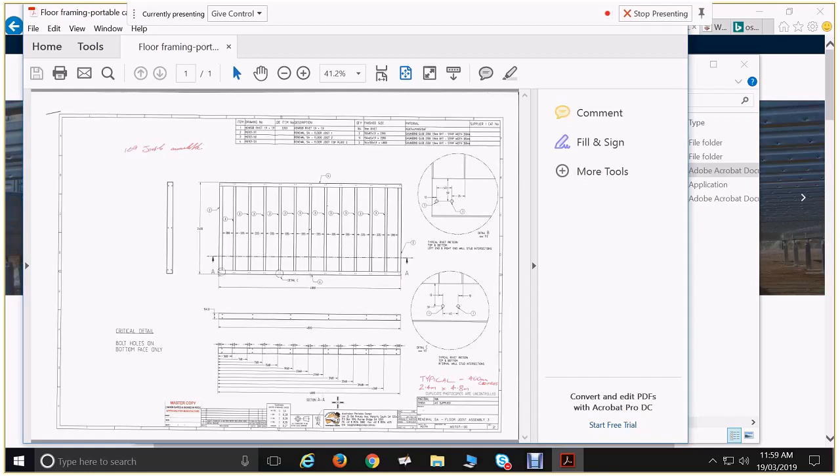So there's a place called Portable Camps. I think if they start supplying stuff to the South Australian market, it'll be a decent, cheap alternative. But anyhow, in the process of stopping out there, having a chat about stuff, I grabbed some of this. This is their engineering information for their limitations on panel sizes, etc. It's much like in your other design guides, saying we've got our various different panel sizes and panel widths and joist spacings and things like that. All that information you need for making decisions about flooring and post spacing and things like that. So there's that place, Portable Camps.